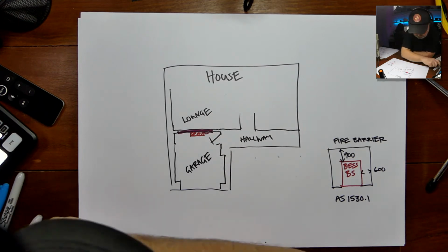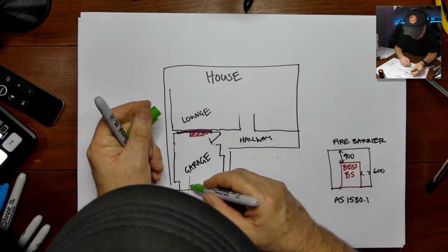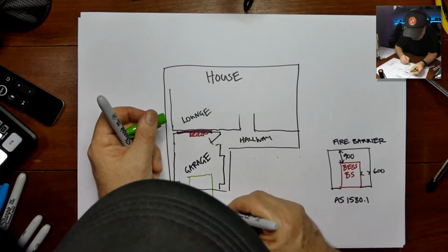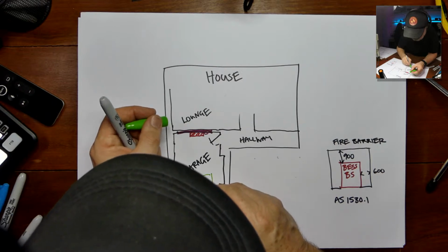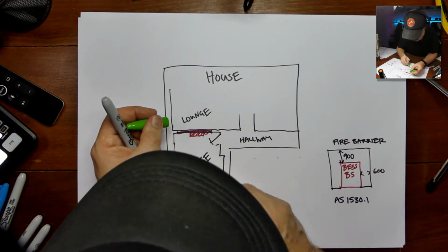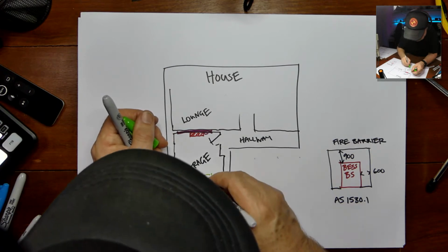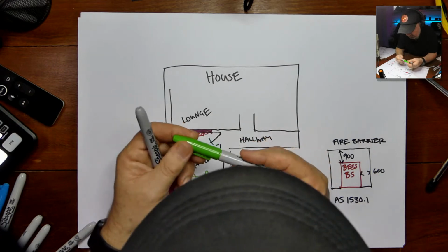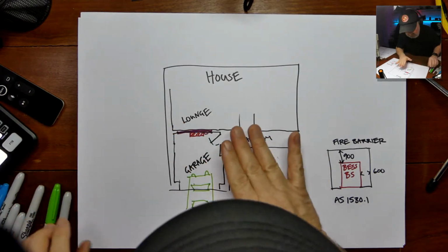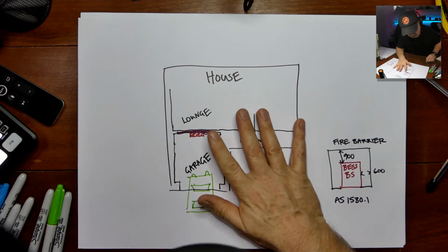And this is when, if you were in the classroom with me, I'd say, what about the car? If you've got a vehicle entering into this space, now this has nothing to do with the battery standard, by the way. This is more to do with AS3000 in terms of mechanical protection. There's our vehicle entering, there's our bonnet, headlights, whatever. It could easily bash into that battery system. So mechanical protection requirements would probably be a guaranteed requirement here.